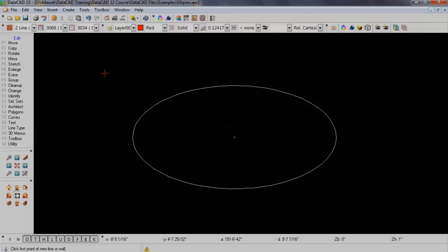Well, I can utilize kind of a trick to turn this ellipse into a symbol and then utilize the symbol clipping feature. This allows me to keep the ellipse as an entity by itself and then still have drawing information around that.